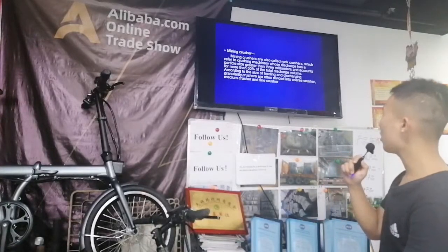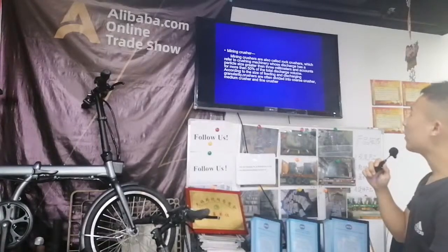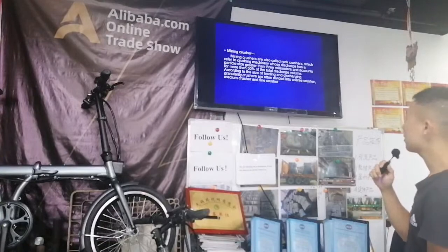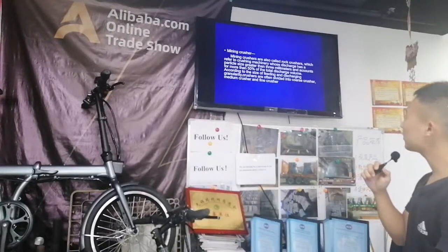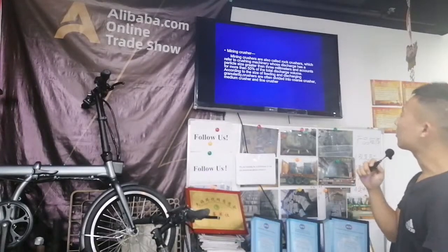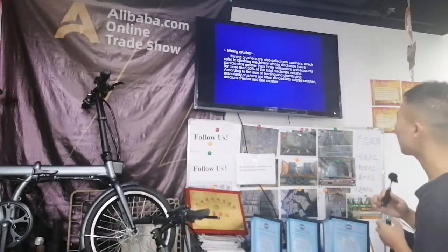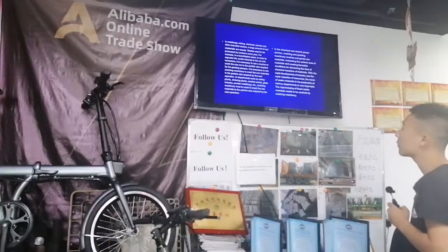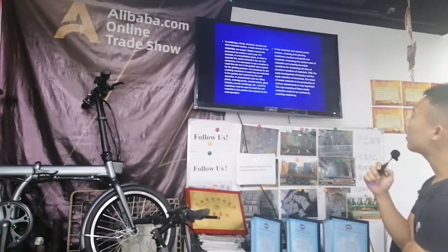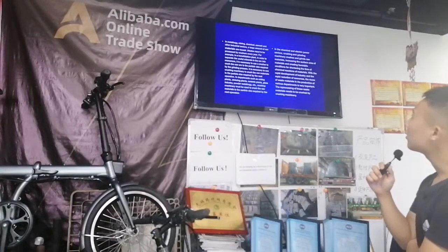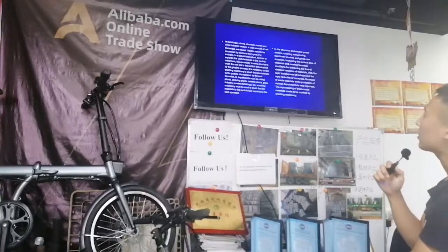Crushers are also called rock crushers, which refer to crushing machinery whose discharge has a particle size greater than 3 millimeters and accounts for more than 50% of the total discharge value. According to the size of feeding and discharging granularity, crushers are often divided into coarse crusher, medium crusher, and fine crusher. In metallurgy, mining, chemical, cement, and other industrial sectors, large amounts of raw materials and waste need to be processed by crushers every year.